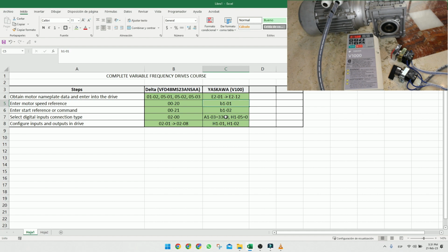And all that was missing left to configure was the motor velocity, which in this case we don't have any external potentiometer, as nothing was included in our drive. So therefore we need to modify our frequency from our keyboard with our arrows up or down. And I also entered our motor data plates just so we don't waste time.